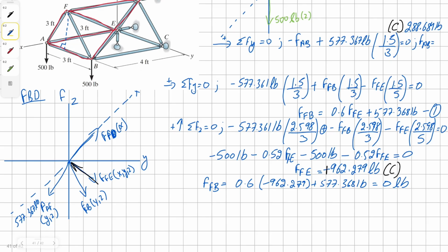Now we can sum the forces in the x direction to find our solution for member FD. I'm going to need the negative x component of force FE.